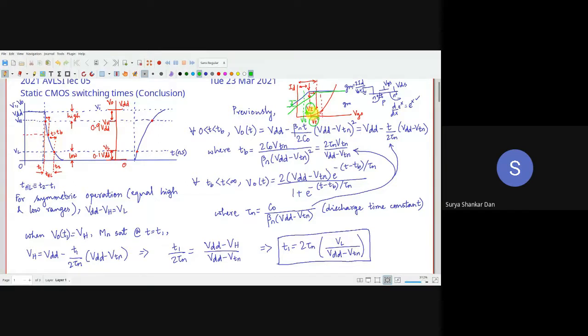But in fact, the erroneous or incorrect Vt, that overestimated Vt is actually helpful for the IC. May not be theoretically correct. So if I ask the students, find the threshold voltage of the device, they will actually calculate this. And if they tell me this one, I will mark it incorrect and give you 0. But industry will always go for this because that will help the IC to perform even after 2-3 hours.